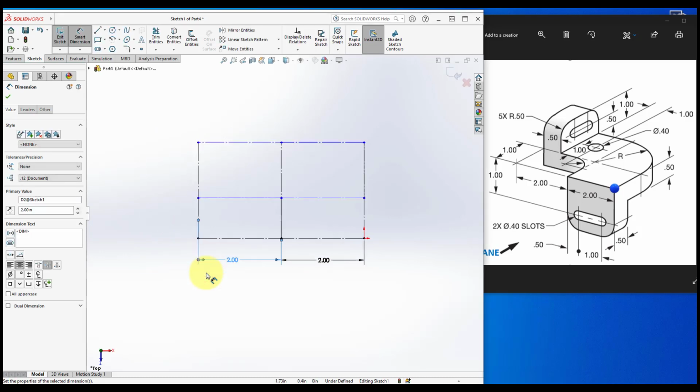So now, if you see that this 2-inch dimension over here, and this line goes up to the center of the radius that's going to go across here. So if this distance here is 2 inches, then this distance is 2 inches, so the radius is 2 inches, and then when you rotate through the 90 degrees, that's going to say that this leg over here is also 2 inches. So we'll go ahead and we can put that dimension